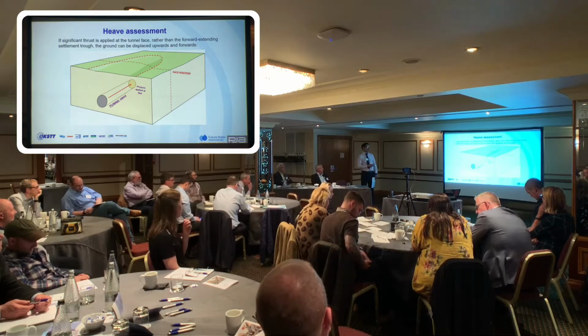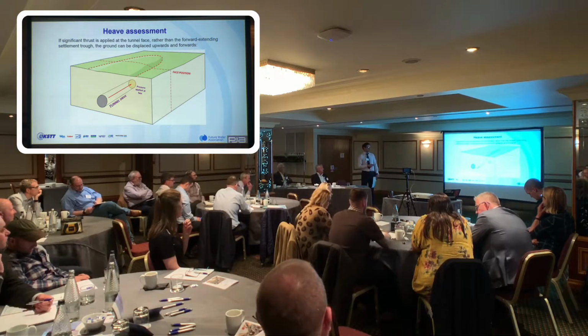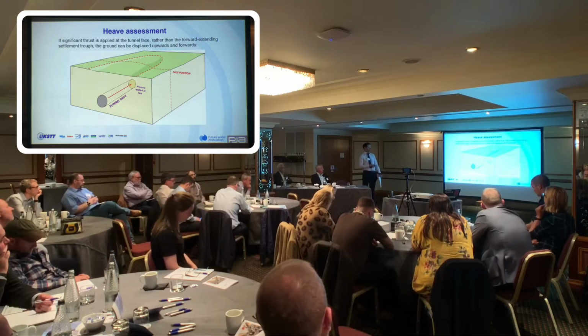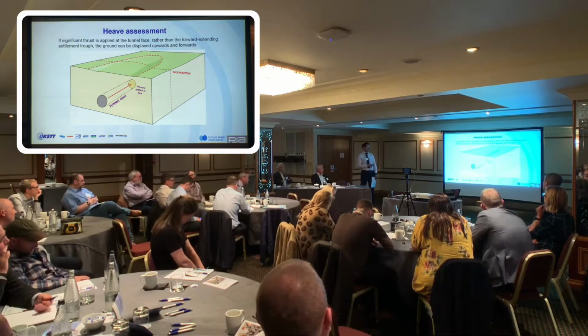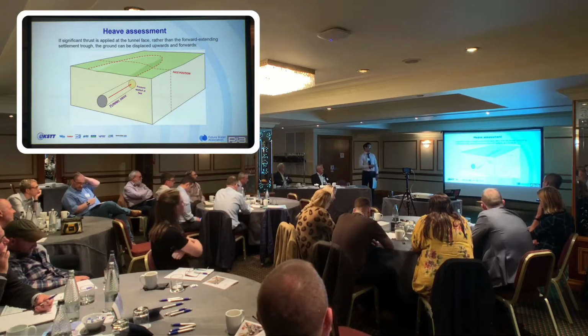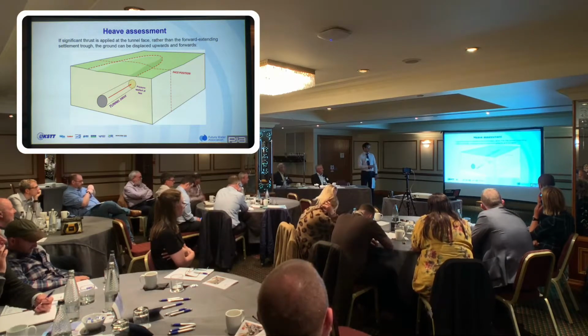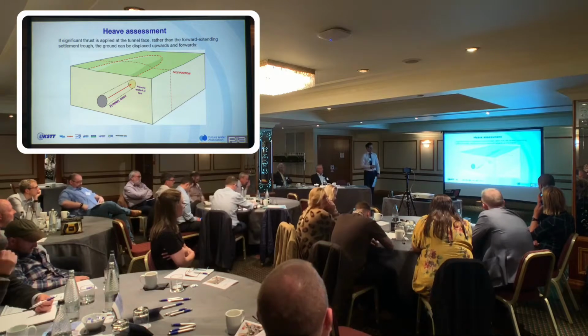Where you've got built-up areas and a lot of congested infrastructure, both underground and overground, then there's probably a bit more detail required. That's where your 3D modelling and your finite element would come into it. And obviously you need to know a bit more ground information as to where foundations are and where there are other services. There could be other tunnels within the ground profile that have to be considered. So that's just a little touch on what we have to consider and how we go about it.